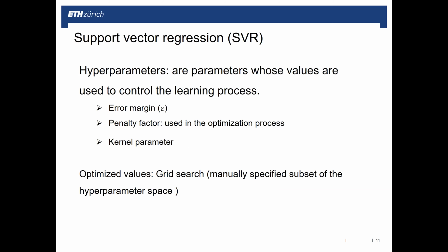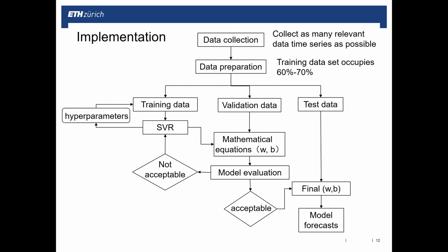And the implementation of these data-driven models is also easy. Firstly, you need to collect the data. Here you should collect as much data as possible which is relevant for the groundwater level forecast, like the precipitation or the pumping rate.